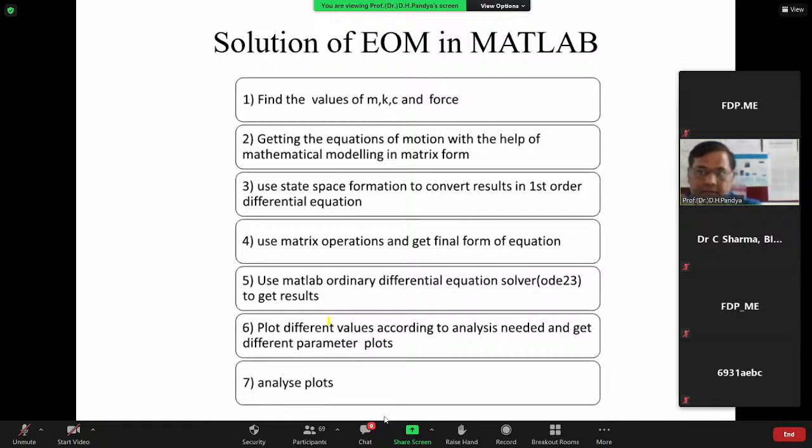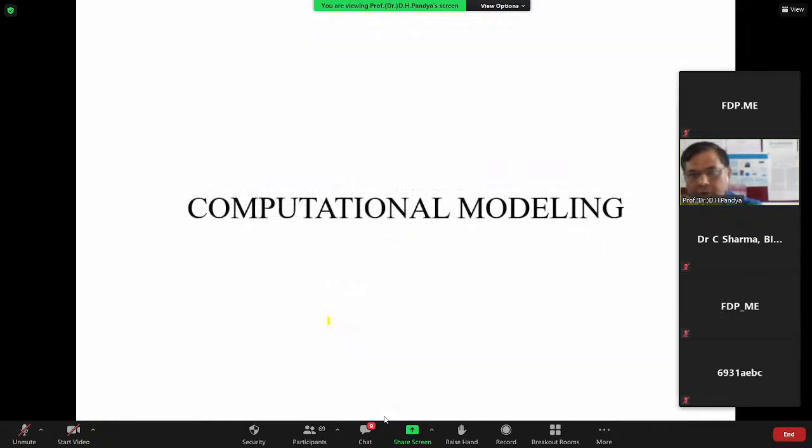Mass, by weighing our different equipment, the insert, seam and the cutting tool. You can weigh directly, and by density you get the mass. Then the value of stiffness and the damping coefficient, c. Stiffness we measure using tap testing or harmonic testing. And c, the damping coefficient, we measure through computational analysis. So computational analysis we also made over here.